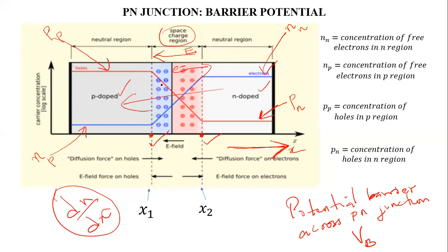When the diffusion continues for some time and sufficient positive and negative ions are formed across the p-n junction, those ions generate sufficient electric field such that the resulting drift current cancels out the diffusion current. So instead of electrons transferring in this direction, under the action of this drift electric field, those electrons will be repelled back, and there cannot be any resultant current across the p-n junction.